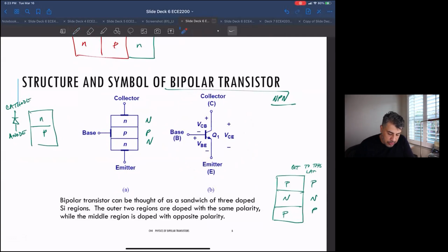Okay, and here's the circuit symbol for the bipolar transistor. Same thing, it just looks different. And so the arrow is always on the emitter side. Okay, so wherever you see an arrow, it's your emitter. And the other one is the collector, and the base goes into this, the hat part, whatever you want to call it. Now, for some reason, and I don't know why Spice did this, but usually bipolar devices have names that start with Q. And if you're doing Spice, which is a simulation program, you just have to start the names of those things with Q. So that's why it's Q1.